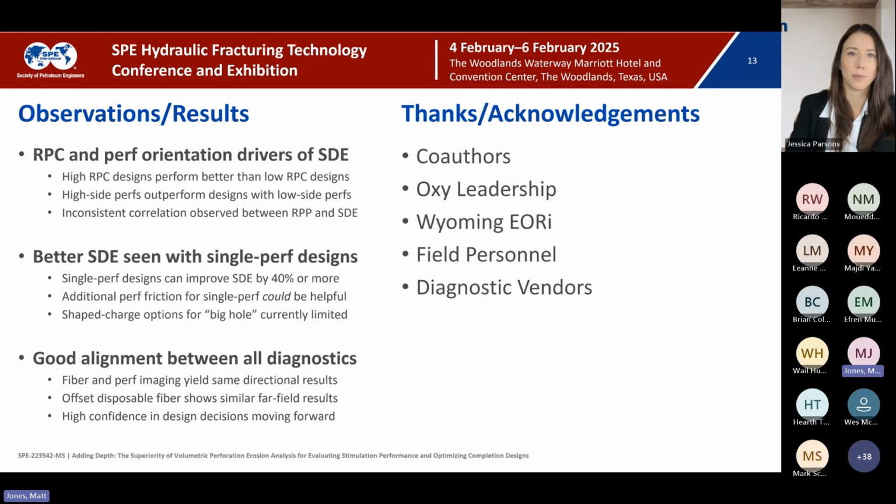Typically what we would do with a fiber optic project like this is we would come back during production and do DSS RFS analysis, which is distributed strain sensing Rayleigh frequency shift. That gives you micro strain measurements going from producing to shutting conditions, or from initial producing to time-lapse producing conditions, where you can see the strain change along the lateral. And you can use that to infer the level of production uniformity and try to correlate that back to stage performance or different design parameters.